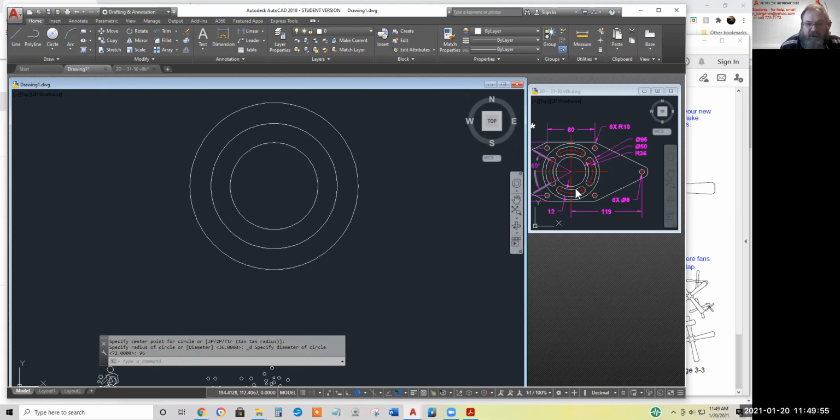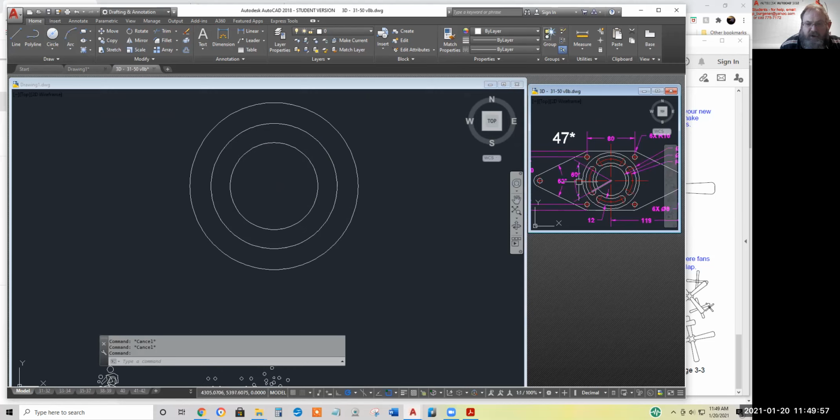Now everything is on a 30-degree increment. Notice 60-degree here, that's 30 up and 30 down. So it'd be a good investment to set our increment to 30 degrees instead of 45-degree increment. That way I can draw some guidelines to form the centers, or the ends if you will, of the circular ends of the jelly bean.